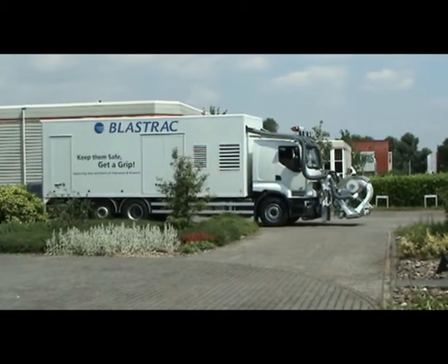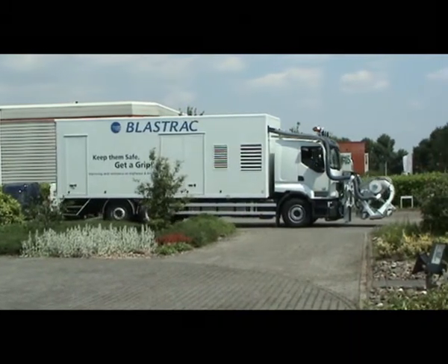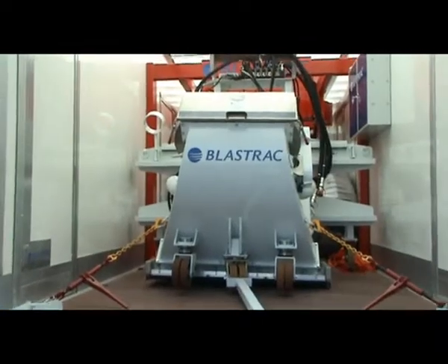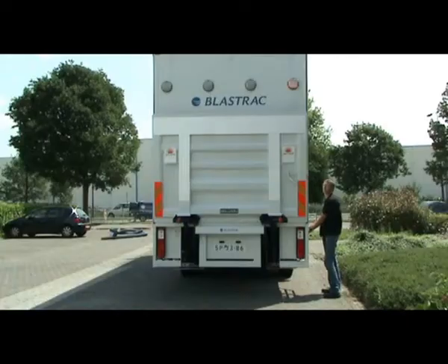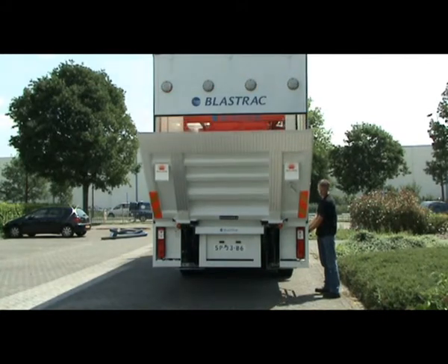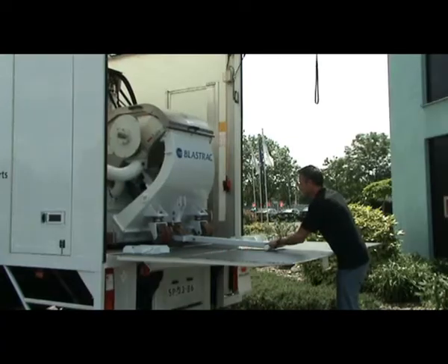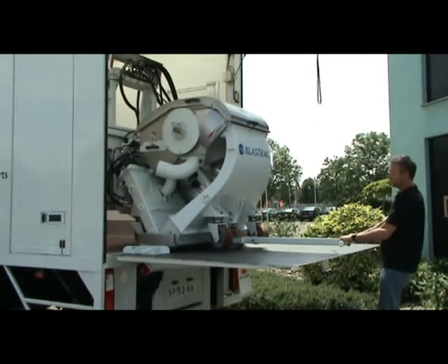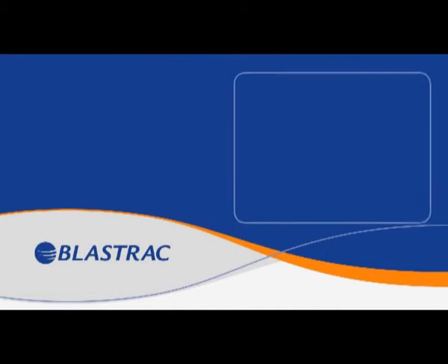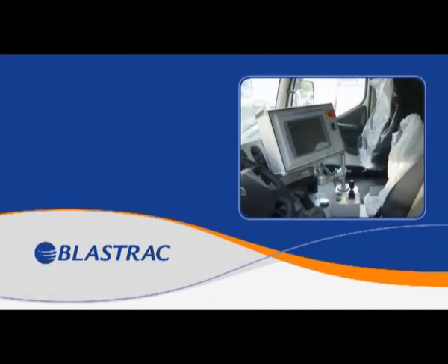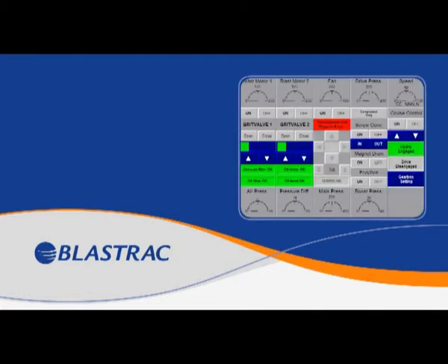First thing to do is unload the Blastrac 2-45D blast head that is stored and secured by a wheel lock system, heavy load binders, and straps in the back of the truck by using the tail lift, which is specially made for heavy loads and has a long lifting plate with special tools to secure the blast unit. Now switch on the PLC unit using the touchscreen panel inside the truck cabin. Engage the hydraulic system by switching to it using the touchscreen system and mechanical clutch of the truck gearbox.